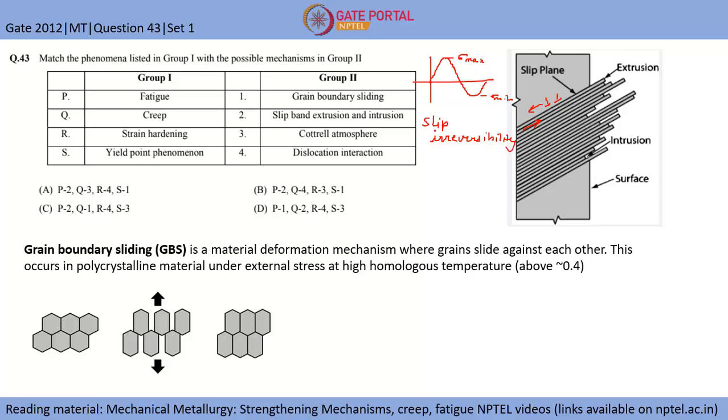So basically the dislocations which were moving in a particular direction again cannot come back to the same position when sigma mean is achieved. What this makes is extrusion and intrusion. So basically this is the basic roughness of the surface. This creates additional roughness on the surface.